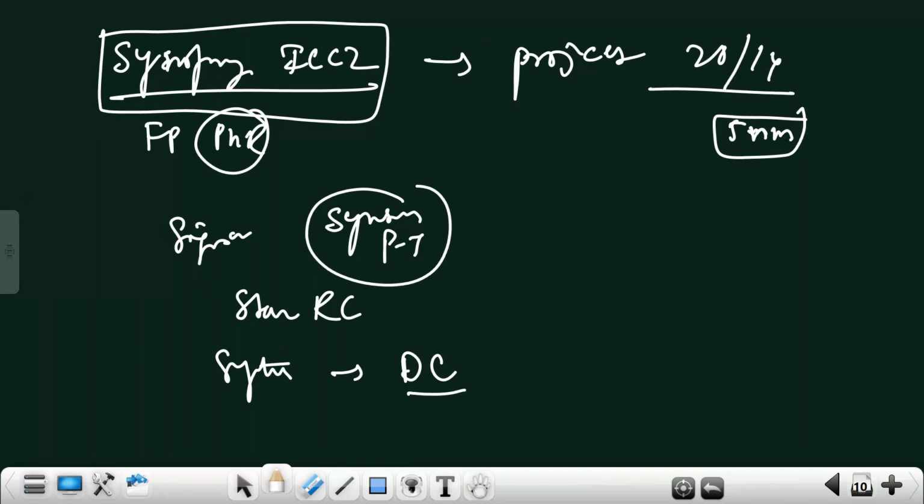So in physical design, you will have more challenges when you are working in nanoscale. It is not similar to what you were testing in PCB, where you check connectivity, whether a 90-degree turn is there or not, what the loss is, that there is no breakage. It is not that kind of testing which we do in physical design, because when you are working in nanoscale, you have hundreds of problems. Some are material level, some are logical level, some are power level, some are timing related issues. There are many issues.